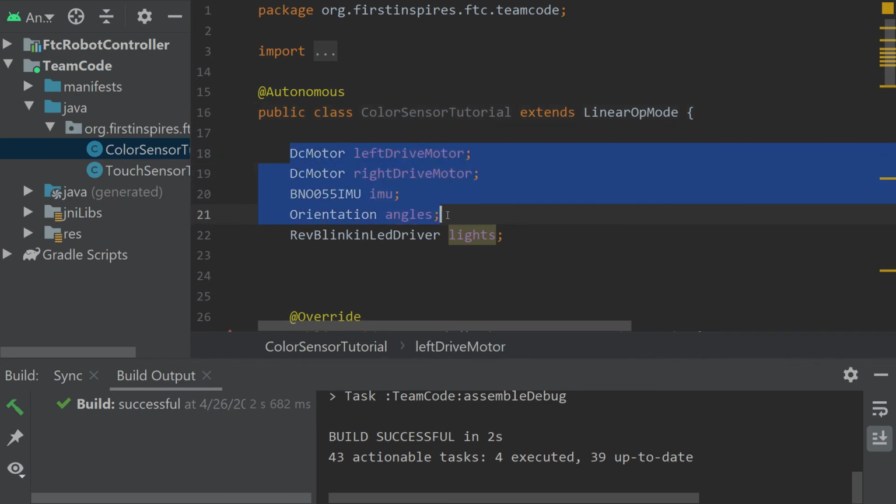I've initialized the drivetrain just like I did in the distance sensor video, except this time I actually initialized the REV Blinkin LED driver because I forgot to in the last video, and I hope this will help in using LEDs with the color sensor. And again, I have the drive forward method that we're going to pair the color sensor with, but it's not specifically for drive forward necessarily. And you'll see that as we go forward.